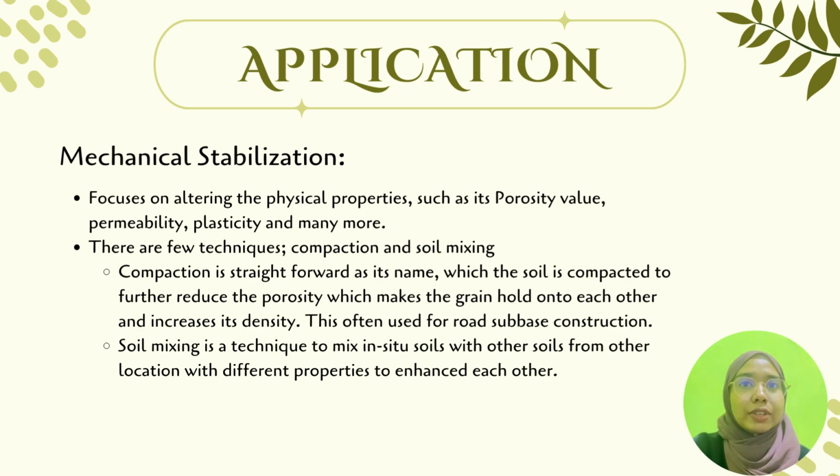It requires physically altering the soil properties such as its porosity value, permeability, plasticity, and many more. There are a few techniques for mechanical stabilization, which are compaction and soil mixing. These two are commonly used on construction sites.